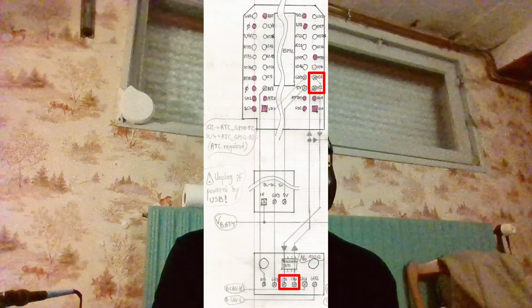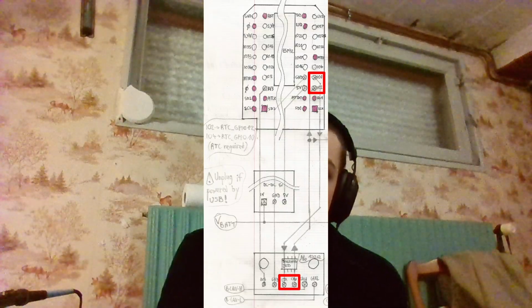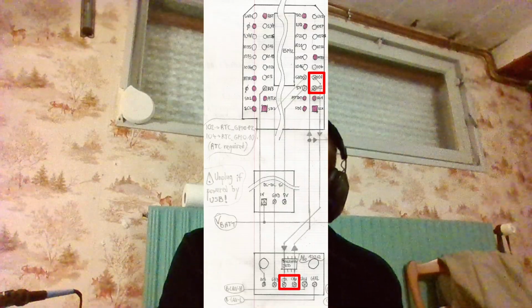But unfortunately, I had a surprise. I don't have the wiring diagram of the microcontroller board, and it happens that on that board there is a blue LED connected to IO2. So whenever the CAN bus transceiver is connected, there is a blue light that is on.